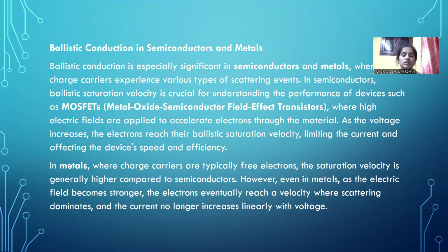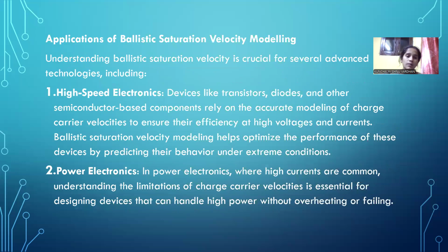As the voltage increases, the electrons reach their ballistic saturation velocity, limiting the current and affecting the device speed and efficiency. In metals, where charge carriers are typically free electrons, the saturation velocity is generally higher compared to semiconductors. However, even in metals, as the electric field becomes stronger, the electrons eventually reach a velocity where scattering dominates and the current no longer increases linearly with voltage.